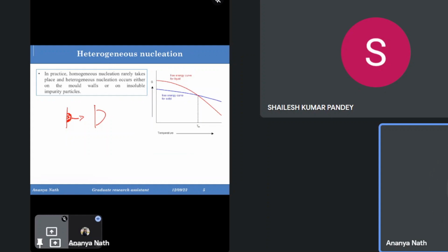There was a graph like this. This is telling us about the delta G. The volume free energy gives the free energy difference between the solidified and the melted region and their interface. That interface is a very important zone, because it experiences force between the solid and liquid, due to the liquid or solid surface energy and the volume energy. Even when this half spherical nucleus has grown, the periphery of this nucleus is not solidified. Inside this periphery, inside this dark portion, it is solidified.